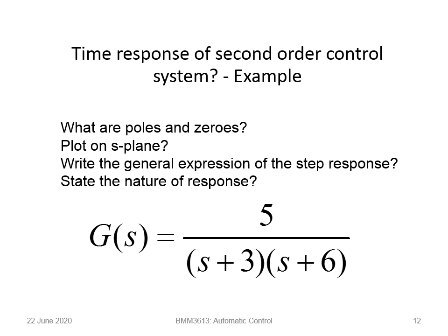Now we have the next exercise and the next example. Let's do this together as well. So we have 4 questions, same as in the previous slide. The first question, what are the poles and zeros of our system? Poles, it's easy. We have one here, one over here, 2 poles. The poles are sigma 1 equals minus 3 and sigma 2 equals minus 6. Why? Because these are the values that turn the denominator to 0, or the transfer function into infinity. So these are the values of the poles of our system.